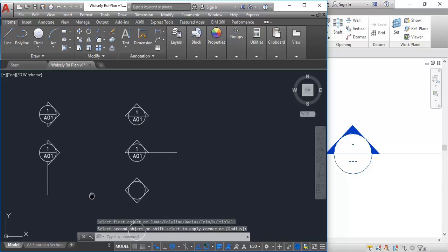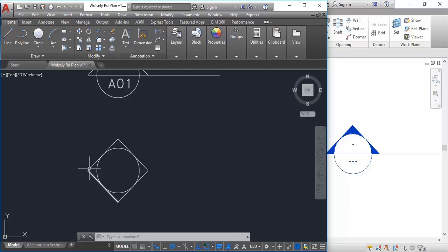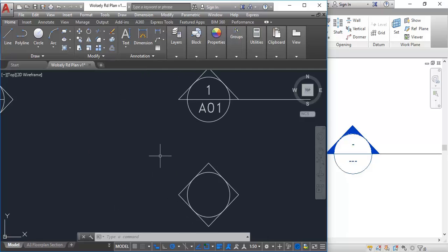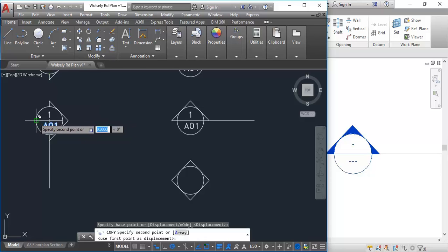Okay, so that's easy. But then if you have a reference like this, where you have several elevations on the one reference, now it can be a problem. You've got to think about it if you have lots of sheets, but that's why it's good if you can keep all of these, if they're referenced from the one symbol, try to keep all those elevations on one sheet, and then it makes your referencing easier, as well as making it easier for other people to read.